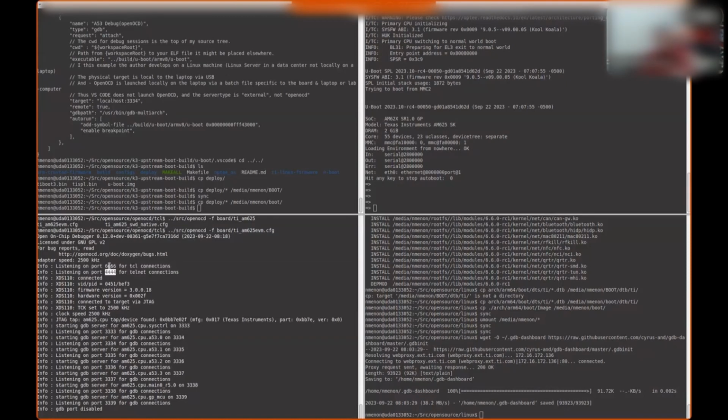Now, that said, there are 2 additional network ports that are of interest too. Port number 444 and 666. These 2 network ports allow for automation. So you can do a local telnet to 444 and directly talk with OpenOCD without using GDB. For example, there is something called the memory AP port. You don't need any of these processes to look at the SoC memory. So Debug SS has a port directly into the SoC fabric. So you use the mem AP port and you can dump registers, look at DDR content, even without touching a single processor.